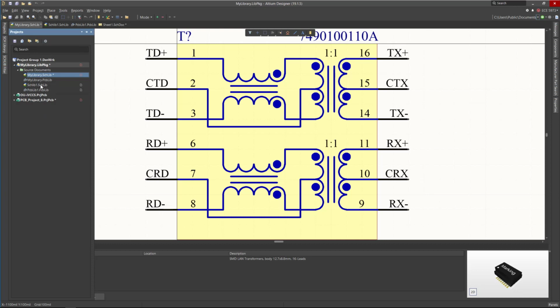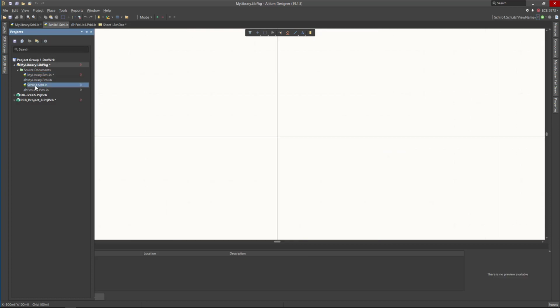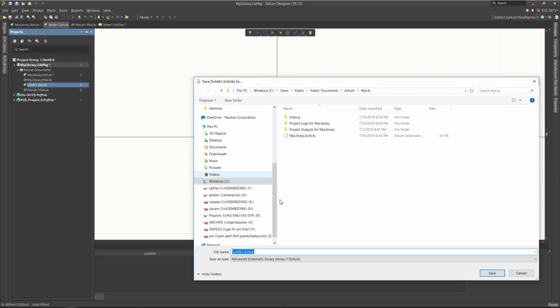You know that this schematic library is dedicated to resistors or passive components, this one is dedicated to integrated circuits, and the other is dedicated to analog components or operational amplifiers. When you come here and edit, it's very easy to handle these parts or transfer them between the libraries. So let's save this library and call it passive.